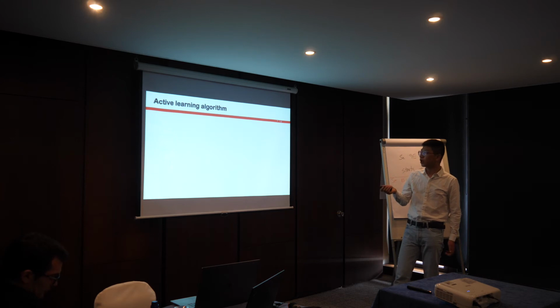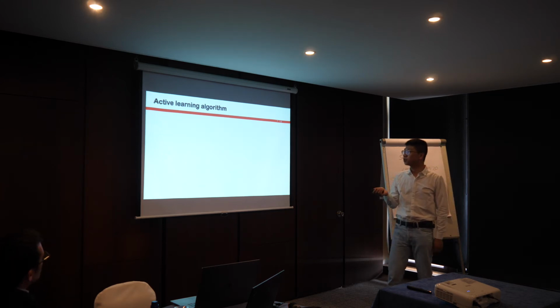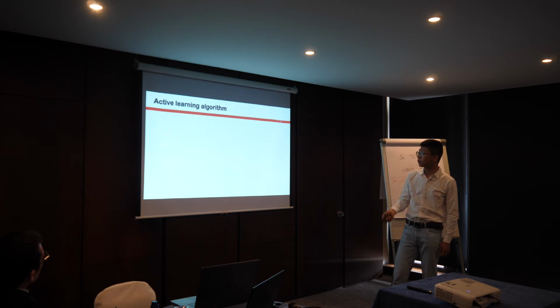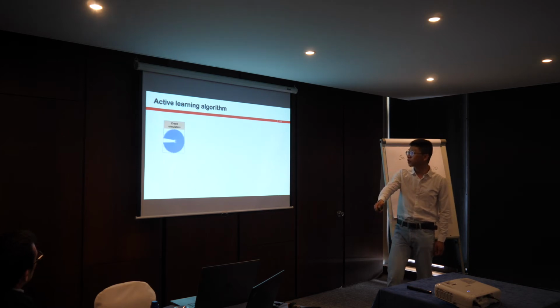But by adding this data, we did the key test, and we found that this is still not enough for GAP to predict fracture. So we developed an active learning algorithm to let the potential learn the crack tip environment. In this algorithm, we first do a crack simulation. During the crack simulation, we detect extrapolation by comparing the predicted error.